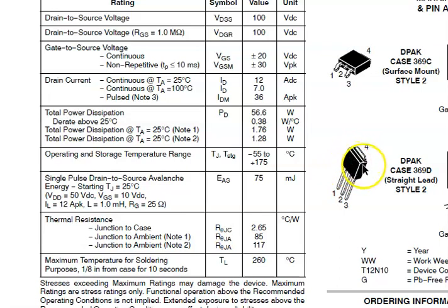part to a heatsink. So what you have to do is either solder it directly into your board here, or you can clip it to the heatsink. You cannot screw it. So either one. If you clip it, at the back of this part you have to put thermal paste. If you solder directly to the board or the PCB, the connection will be in firm, direct contact with the PCB board.